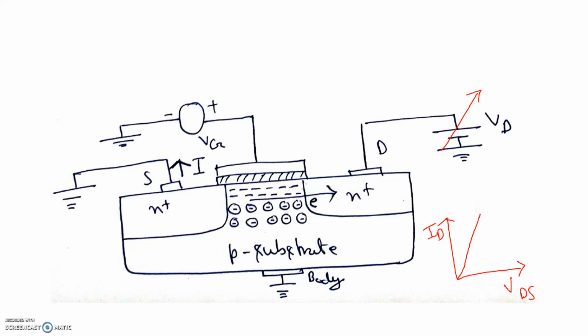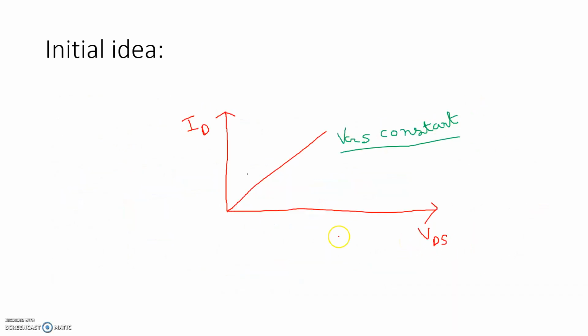As a result their potential energy will decrease and kinetic energy will increase. Increase in kinetic energy means increase in vibration in the charged particle, and as a result the mu or the mobility decreases, and velocity decreases, and for that the ID or drift current goes to some saturation value at a high value of VDS. This we got as velocity saturation.